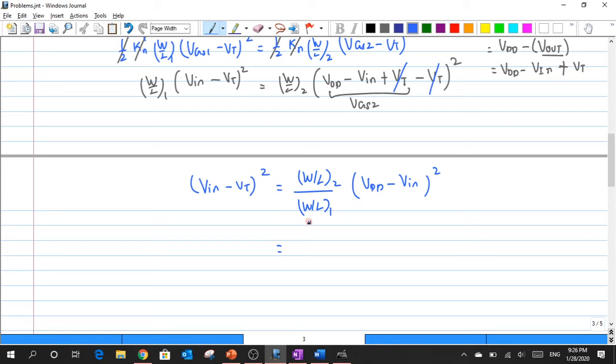When we do so, since we are dealing with NMOS transistors, the VOV of each of these transistors will be a positive quantity. So when I take a square root of this quantity, I could happily end up having just the positive value rather than holding plus or minus, right? So that is what I'm trying to use here. This square root would end up having a positive value, and on the right I retain this Vn minus Vt.